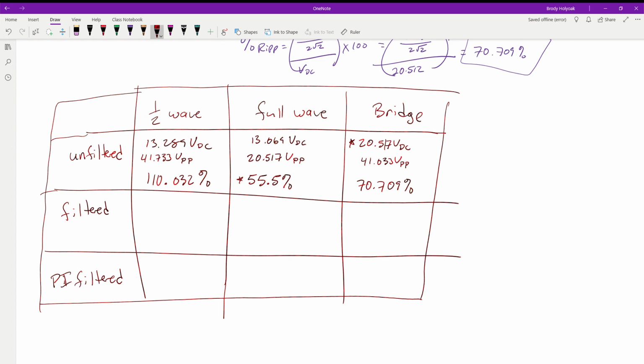So we're going to see this drop in its minimum voltage, or I guess increase. But what we're going to see is the decrease in the total amount that it's changing. And one of the things we can manipulate is by changing the capacitor and the resistor to increase or decrease that time. How long do we need it to be discharging for before it says, okay, I'm done, and starts charging back up. And so those are some of the knobs and levers that we can turn and adjust to get this thing to kind of sing and dance, to dial it into where we want.